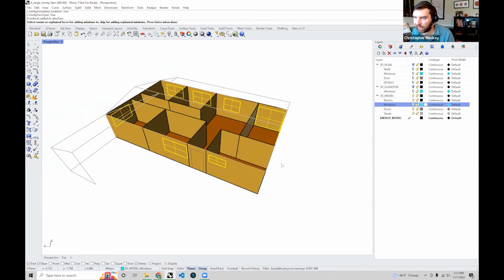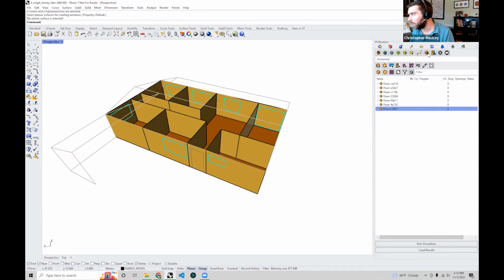as long as you get all those selected and you hit enter, the command, oh, actually, I'm sorry, I did the command incorrectly. I always do this. Actually, the way the command is structured, and this is why I have to read the prompts here, I just hit escape to get out of this. When I say select geometries, you'll see it first asks me, I should always read this, to select the orphan faces or rooms to which you're adding the window geometries. So this is even before you select the actual windows. Just make sure you select the rooms.